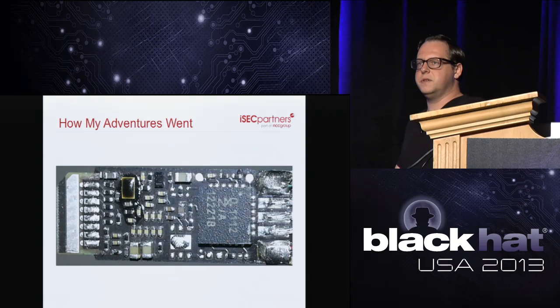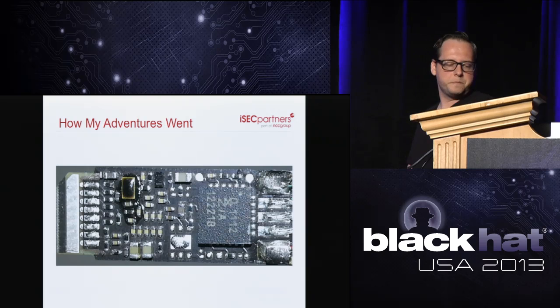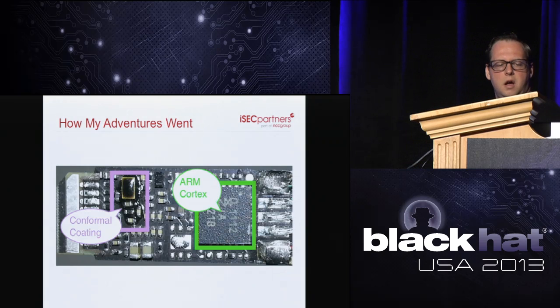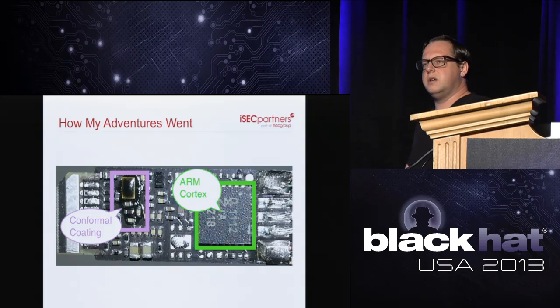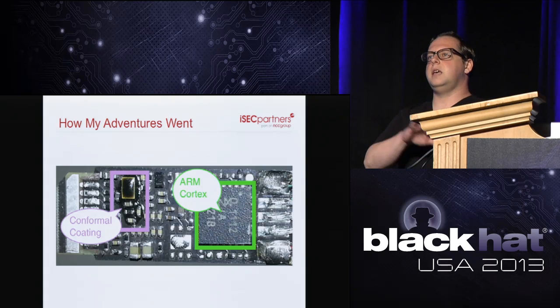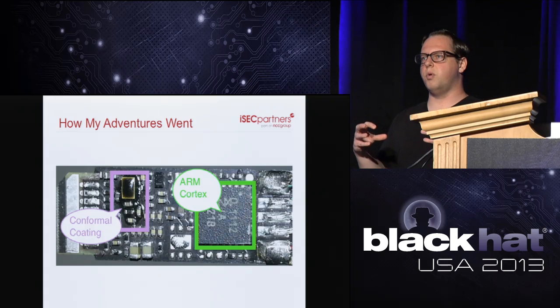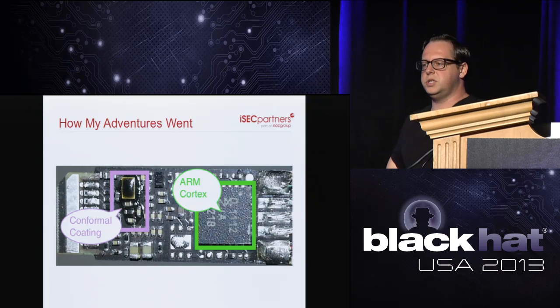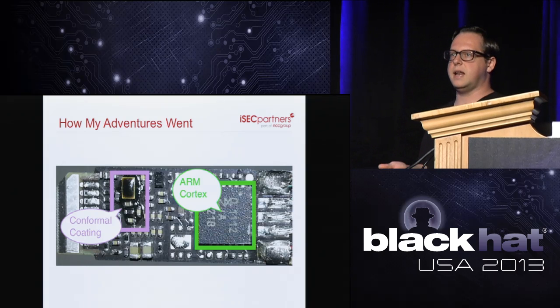We have the data sheet for this. It's the same data sheet as the one we were looking at for the other one, so that's a win for us. Also, we noticed this goo over here. What appears to be conformal coating. Conformal coating serves two purposes. The first purpose is it locks down the board and prevents interference. With these high-speed transmissions and this small space we're working with, it's essential to not have any interference.